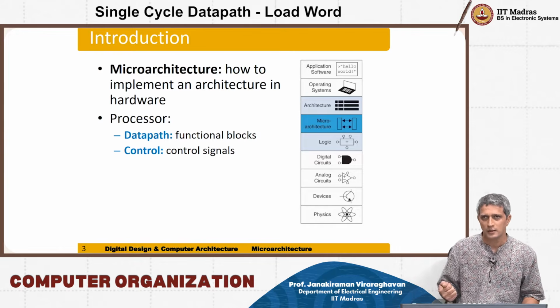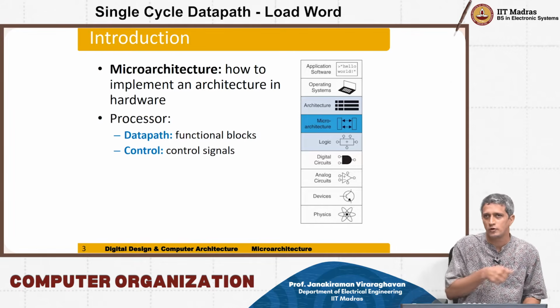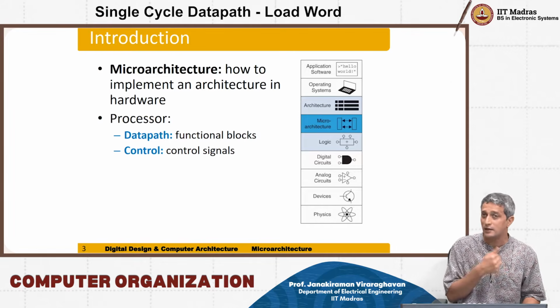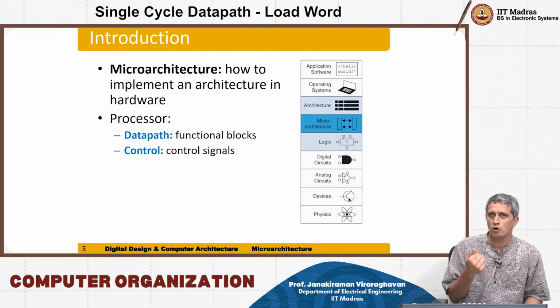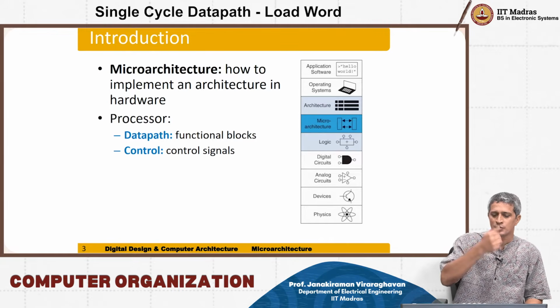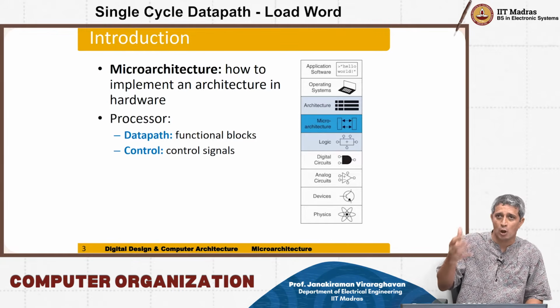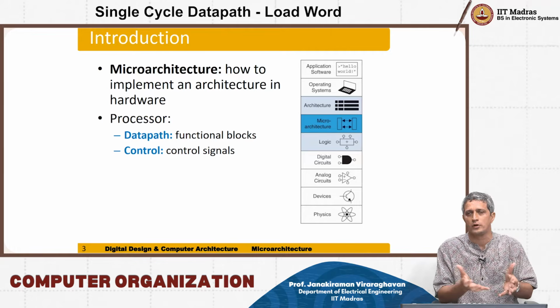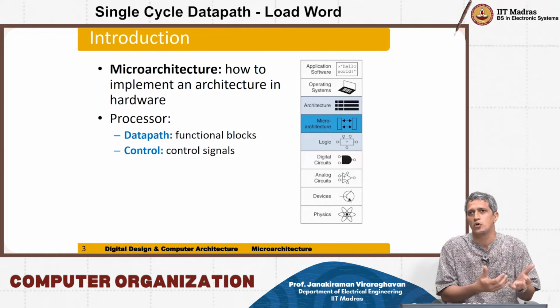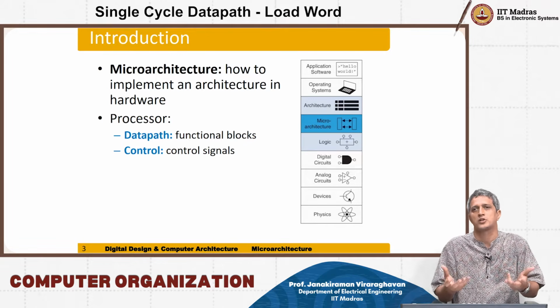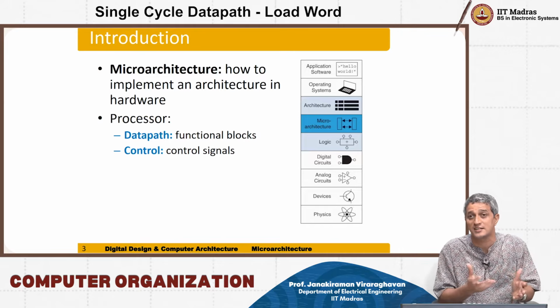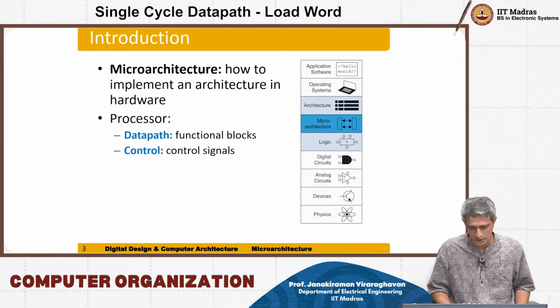One is the data path, how the data is actually going to flow in the processor, and another is a control path. The control path is basically the block that takes the machine code from the memory and is going to decode and instruct the processor to do certain operations in a certain order, right? That's the key point here.